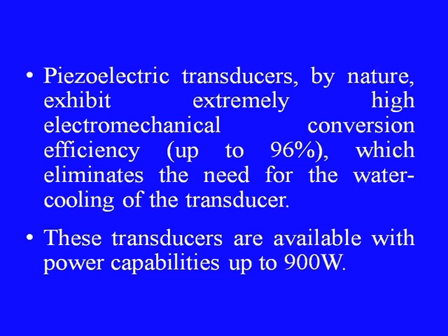The power supply depends on the size of the transducer. Piezoelectric transducers by nature exhibit extremely high electromechanical conversion efficiency, up to 96%, which eliminates the need for water cooling of the transducer. Otherwise, this heat generation in the transducer is also a major problem.